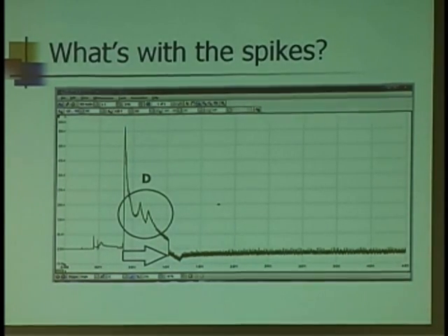The engine's starting to move. That's the first few cylinders. What I want to look at, though, is how long it took from the time I turned the key to start until the motor was running on its own. Generally, about a second or so is good.